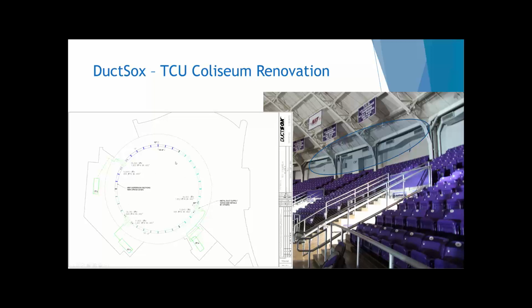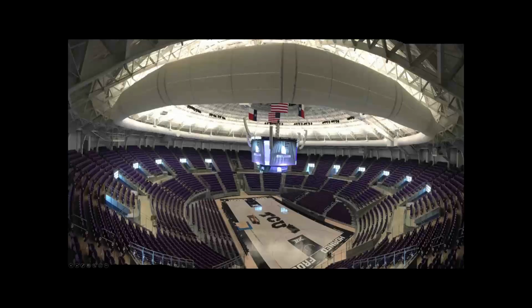a 60-inch diameter ring in the middle, where it would throw at the occupants as well as into the middle. So it provided a really well mixed system. It turned out great. As you can see, this ring has these linear vent orientations, where it's throwing at the occupants as well as into the space to mix that system.